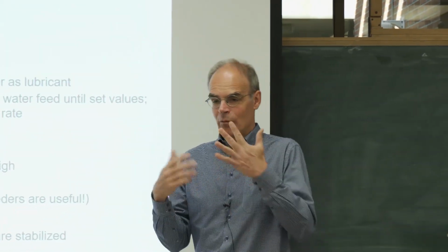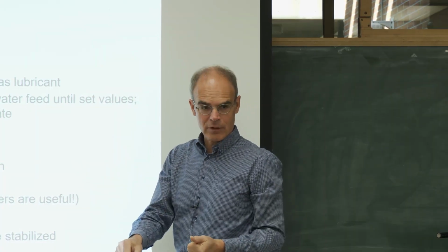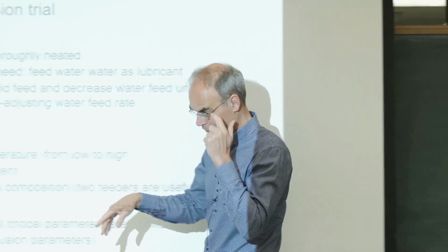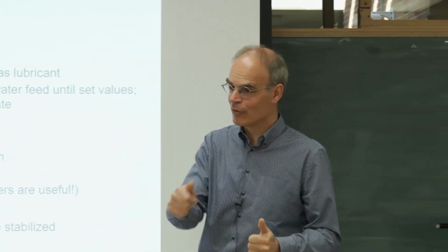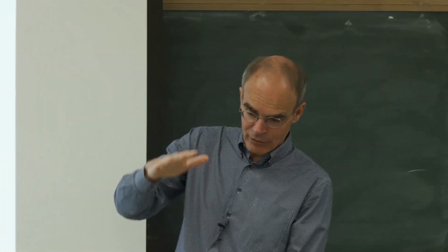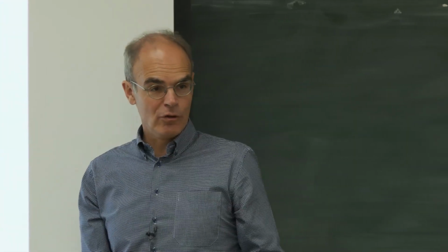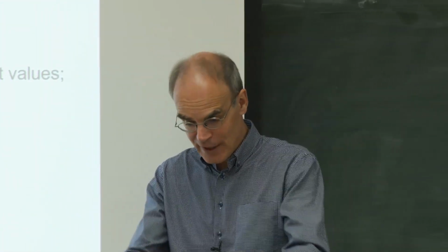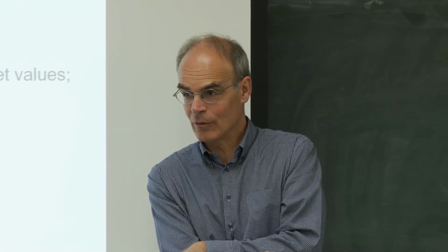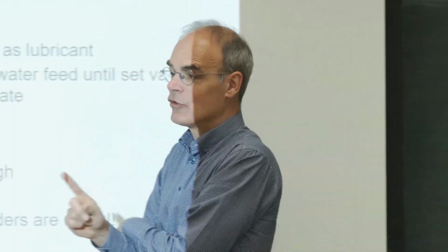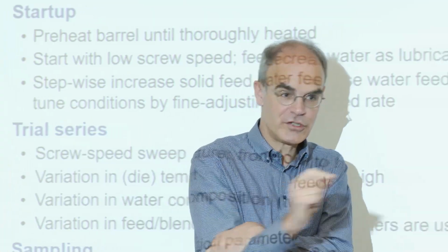The way with one feeder I would usually do it: you have that feeder, so run it down. Usually there's a safety level. Actually, our current one has a very high safety level, so it says empty when you still have a lot of stuff. So we overrule that security the whole time. Run it down until it's almost done, which still is quite some material. Then you can put in your new material, but it will still take some time before you flush out all that mixed material and you get your pure new blend composition. So with one feeder, it is very cumbersome to change over from one blend to another. But still you want to do it.